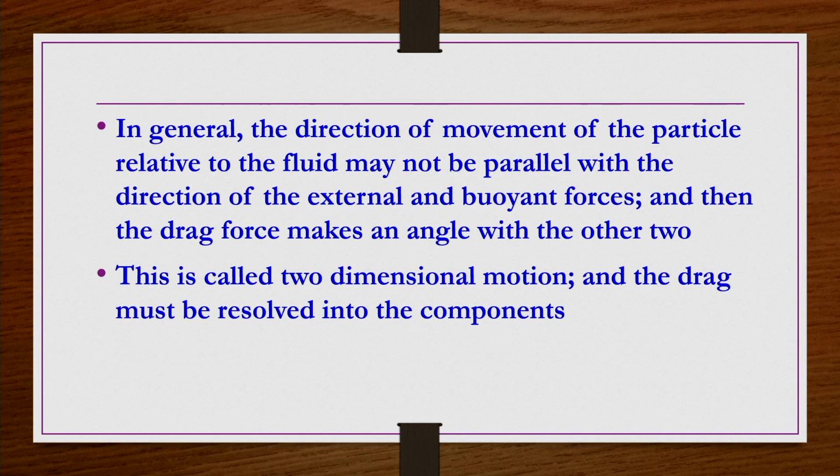So, this kind of case where the drag force makes an angle with the other two forces is called a two-dimensional force in general, and then drag must be resolved into components. Like the individual pressure drag component you have to find out, the individual friction drag component you have to find, something like that. In the previous lecture, when we were defining the drag forces